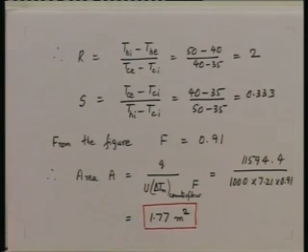So, for different flow configurations, with the help of these two examples, we have illustrated how to obtain the area A for a given heat exchanger. Now, this is one technique, using the equation Q is equal to U A delta Tm.